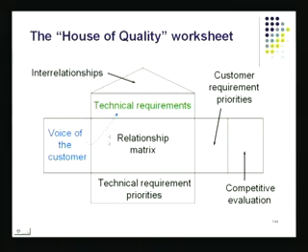So I first talk to the customer, I come up with design specs, then I go to technical requirements, then I go to manufacturing specification, then I go to details of the process and quality assurance. I'd like to travel all the way. To do that, I use this House of Quality structure. Let's take a look at this structure here. I've got the voice of the customer, which basically are the requirements. I've got technical requirements which are put out here.